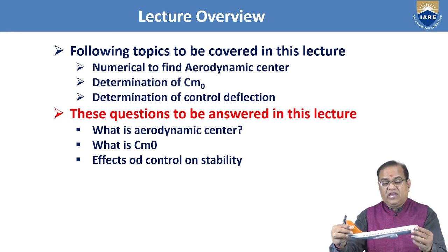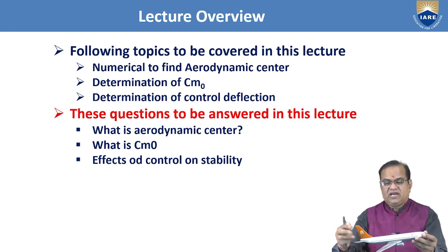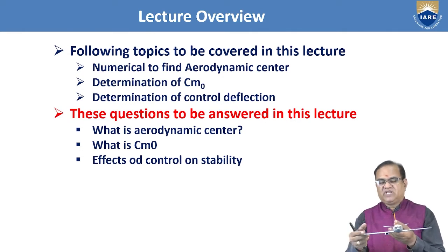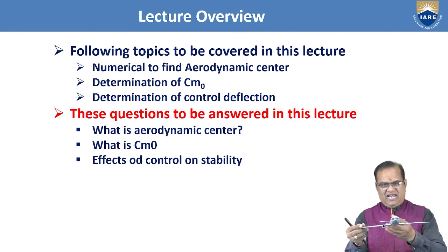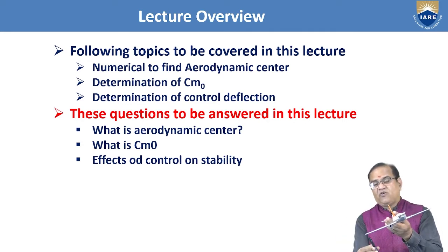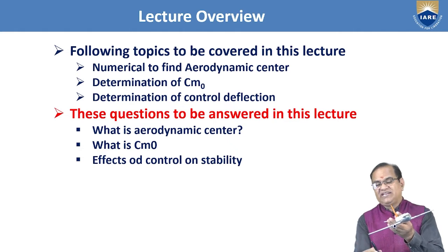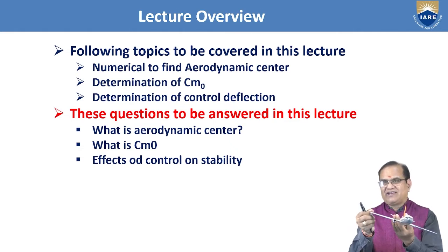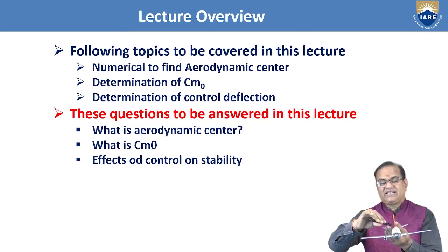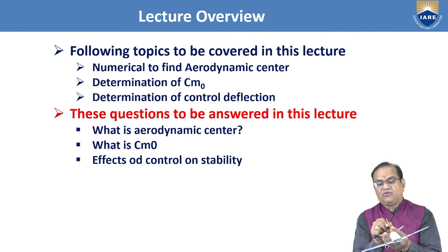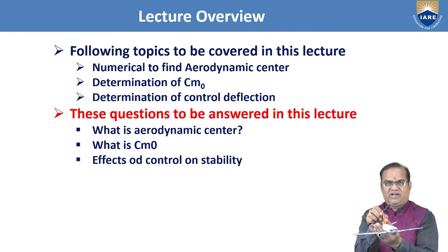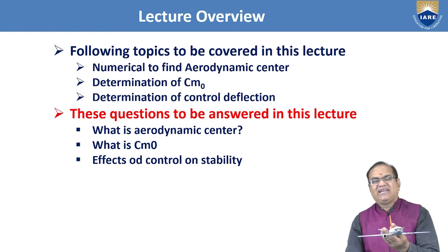So if you are flying like this, with the right wing down, you can see here the aircraft is flying like this, and if you make the right wing down like this, then the wind direction will hit here and it will try to reverse it back. The same thing, the side slip will be generated, and this force will give a moment and this moment will try to restore it in the same direction.